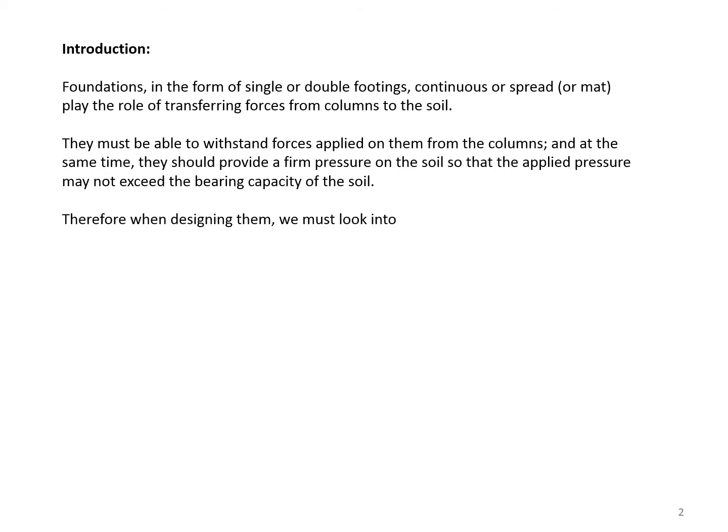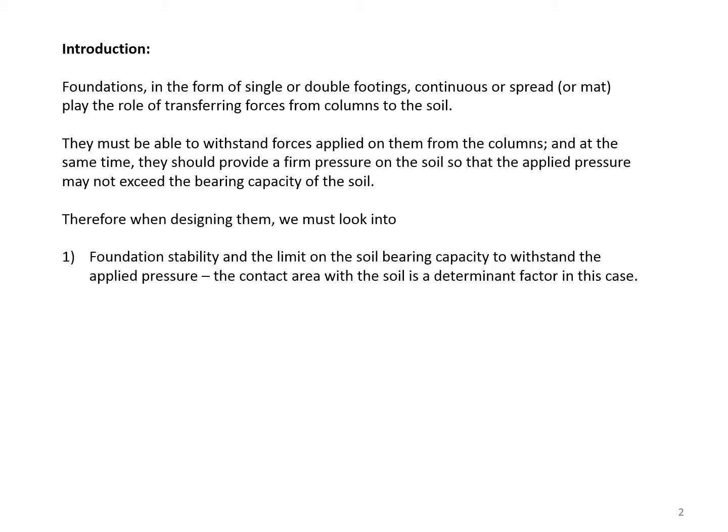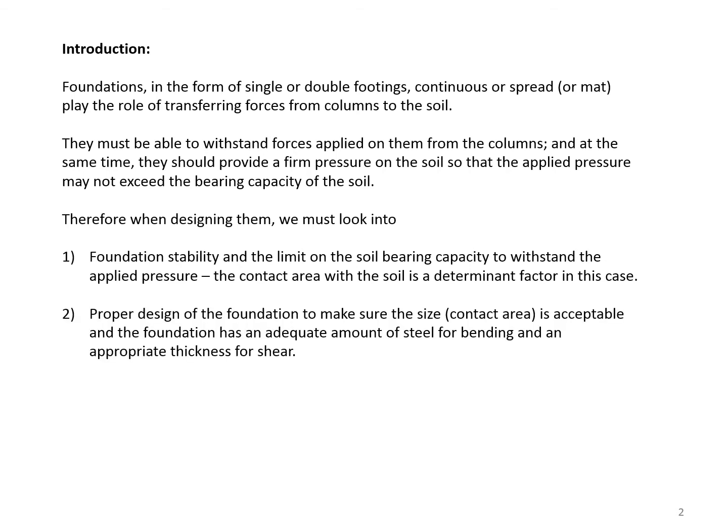Therefore, when designing them, we must look into foundation stability and the limit on the soil bearing capacity to withstand the applied pressure. The contact area with the soil is a determinant factor in this case. Proper design of the foundation makes sure the size, the contact area, is acceptable and the foundation has an adequate amount of steel for bending and appropriate thickness for shear. We also consider the potential for settlement that can occur in short and long duration loading.